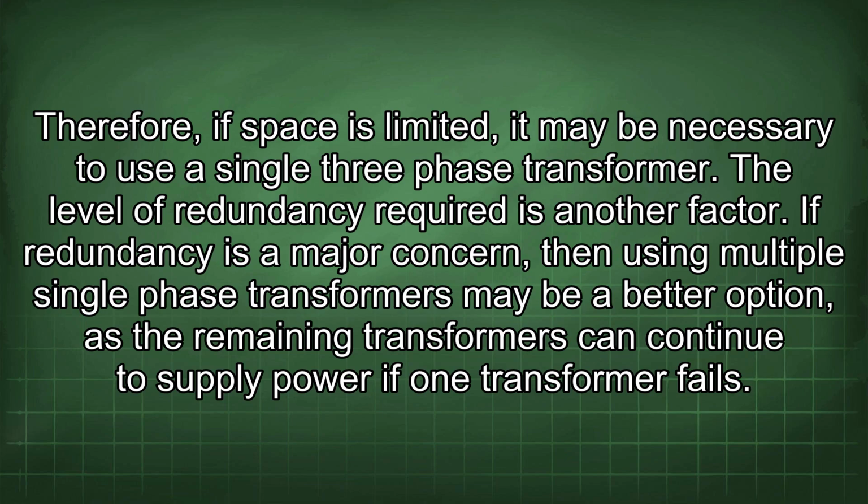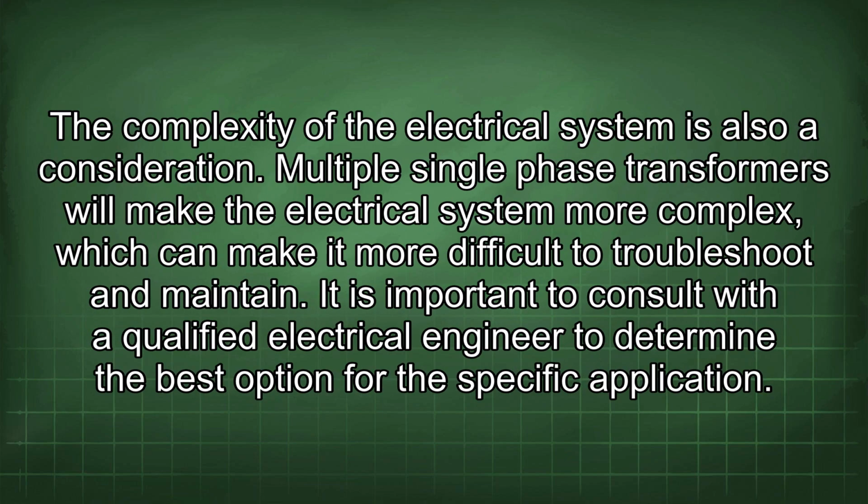The level of redundancy required is another factor. If redundancy is a major concern, then using multiple single-phase transformers may be a better option, as the remaining transformers can continue to supply power if one transformer fails. The complexity of the electrical system is also a consideration. Multiple single-phase transformers will make the electrical system more complex, which can make it more difficult to troubleshoot and maintain.